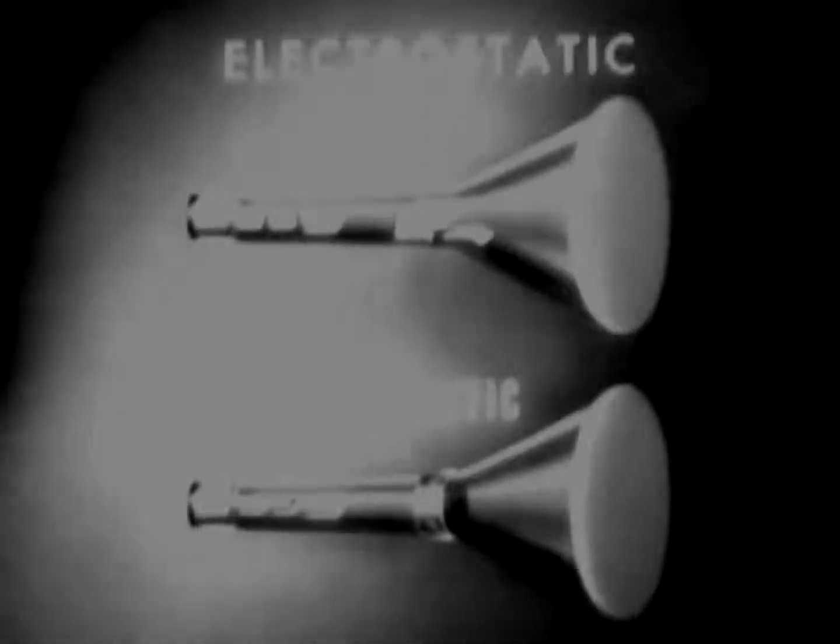First, to review what we know of the electrostatic tube. At the rear end of the tube is an electron gun, composed of a heater, cathode, grid, and focusing anodes. The cathode, when heated, gives off electrons, which are formed into a stream by the grid. The anodes accelerate the electrons and focus them into a beam. The beam bombards the fluorescent coating on the face of the tube and causes it to glow with a bright spot of light. These plates deflect the beam horizontally.